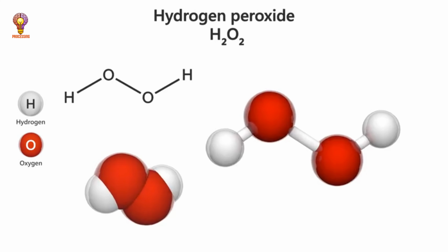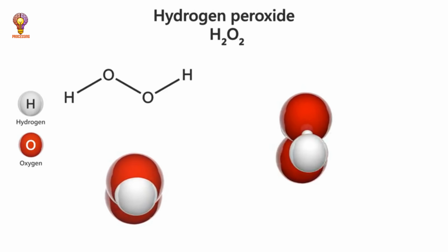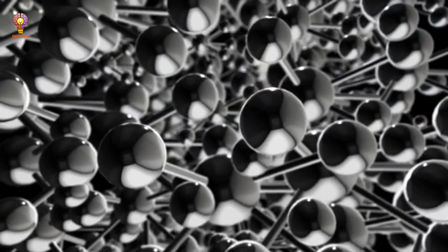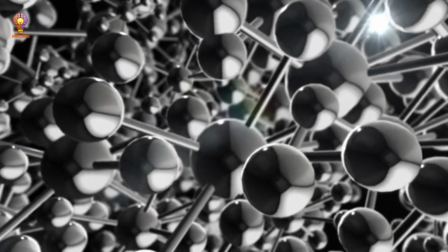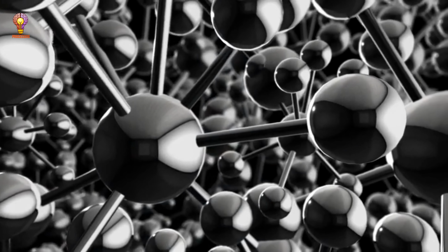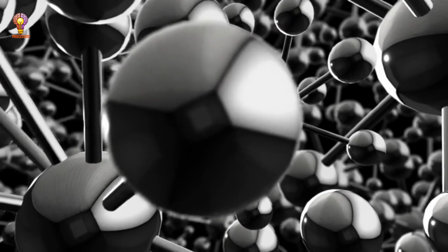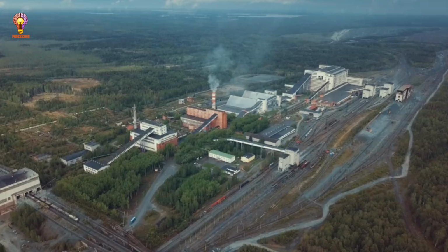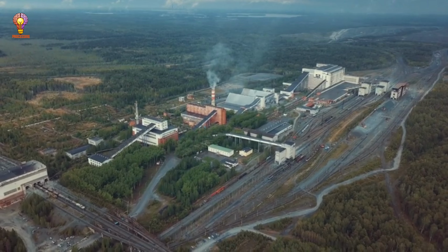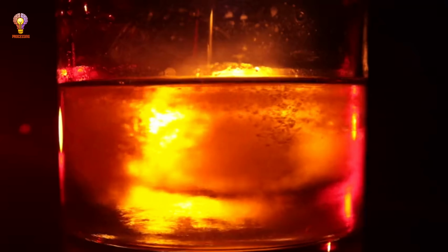Hydrogen-based DRI. The use of hydrogen to replace carbon in the direct reduction of iron ore is a highly researched area. Hydrogen-based direct reduction is seen as the future for green steel, because hydrogen, when used as a reducing agent, only produces water vapor as a byproduct, making the process nearly carbon-free. Sweden's HYBRIT project and other global initiatives are already piloting hydrogen-based ironmaking technologies.